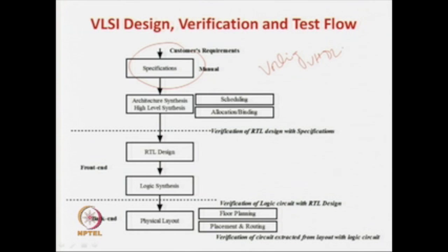That is, for a given specification to be realized, how we can optimally schedule the operators required in the given time steps, and then how individual hardware operators are bound and allocated to these operations. So, this was the high level synthesis part, which we have already discussed in detail in phase 1 of the course, which is on design.